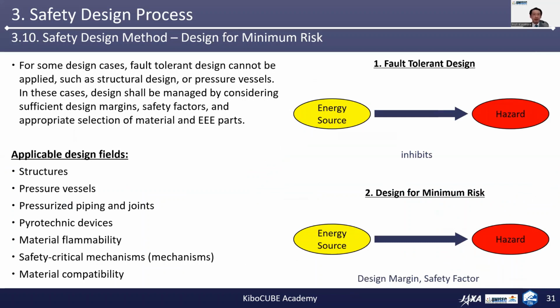So next, I'd like to explain the idea of design for minimum risk. For some design cases, fault-tolerant design cannot be applied, such as structural design or pressure vessels. So in these cases, design shall be managed by considering sufficient design margins, safety factors, and appropriate selection of materials and parts.